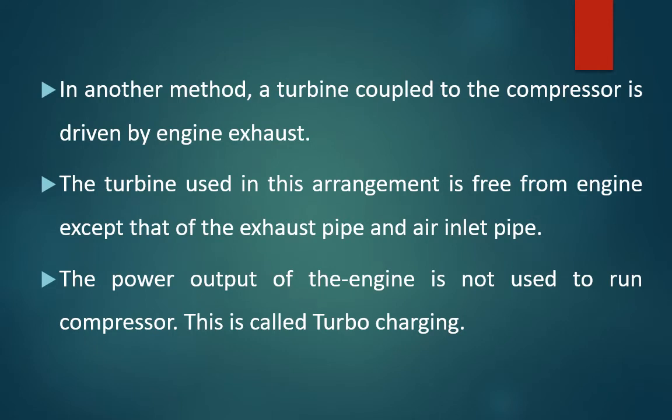So in another method, a turbine coupled to a compressor is driven by the engine exhaust itself. In the previous case, the compressor was driven by part of the power from the engine itself. But here we have a method where we have a turbine that is coupled to a compressor, and this turbine is driven by the engine exhaust.